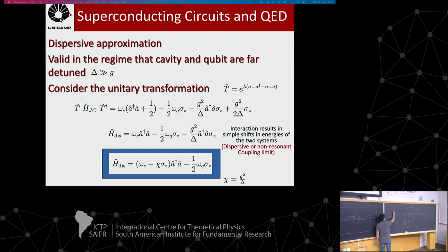You mix this signal with another signal that will be 0.1 gigahertz, 0.2 gigahertz, 0.3 gigahertz. You put this signal for each one of those, you mix with this 6 gigahertz here, and you get all of that signal here. You send it inside. So you have a 6.1, 6.2, 6.3, and 5.9, 5.8, 5.7 as well.